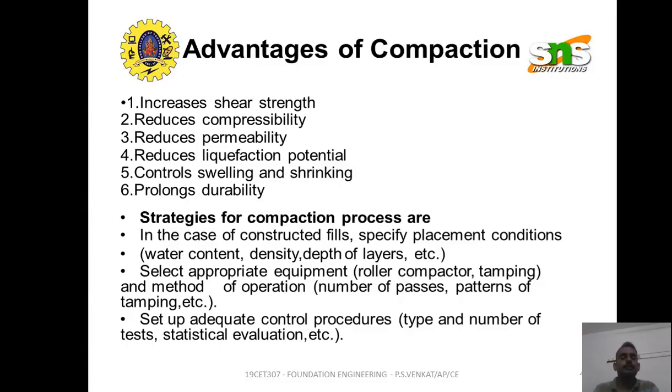The strategies involved in the compaction process are: in case of constructed fields, specific placement conditions such as water content, density and depth of layers are to be considered.